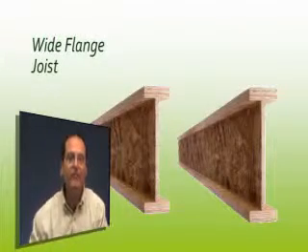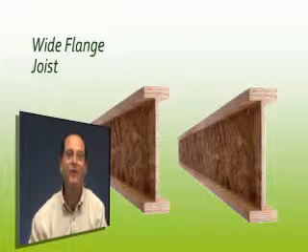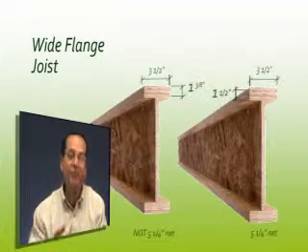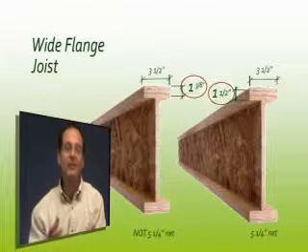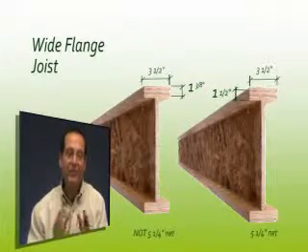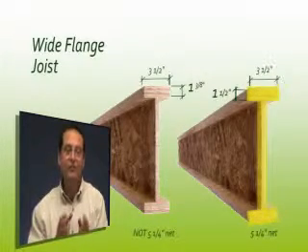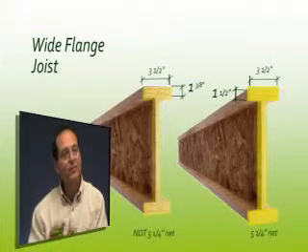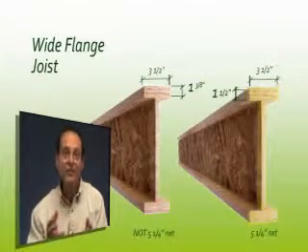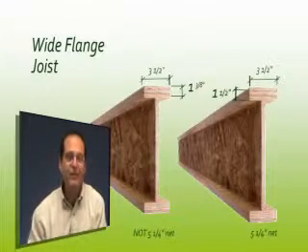Then the joist itself. So you see here the two joists that look remarkably identical, and they are remarkably identical, with the exception of an 1/8 of an inch difference of thickness in the flanges. So the tested assembly is the one that has to be specified. In this case, it takes a full 2x4, 3.5 by 1.5 inch flange, but you can see there's a cousin right next to it that's only 1 3/8 inches thick. Now that's not by accident, it's all by design.